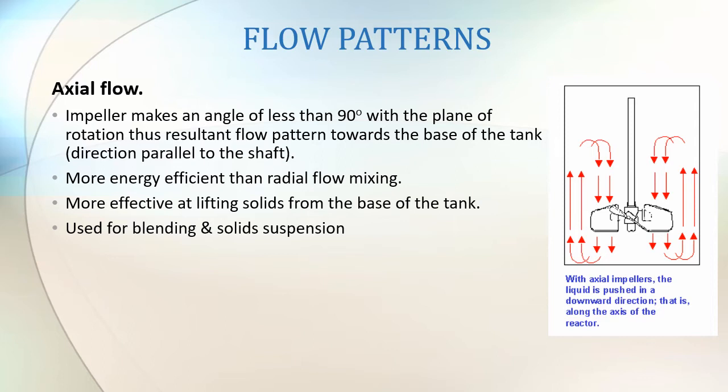So again, the direction of flow is parallel to the shaft. The flow will go down and then will go up. More energy efficient than radial flow. More effective in lifting solids from the base of the tank, and is usually used for blending and solid suspension.